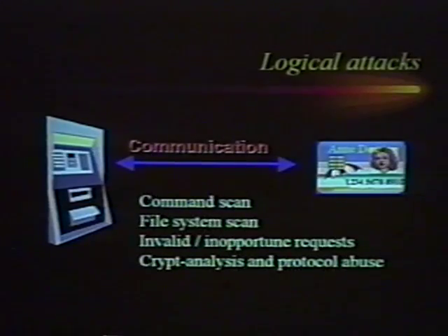I remember an example where a smart card supported a command that meant something like "send last data again." Suppose you're in a communication and you're exchanging data and something goes wrong, you ask the smart card to send last data again, and it retransmits. Now suppose that you ask this question immediately after starting up without any data being sent previously. The smart card may send its complete memory because it's confused about what you really want. So these things happen now and then.